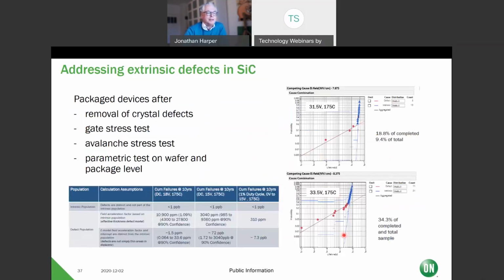So if you look at the classical papers on oxide integrity, you have the intrinsic oxide integrity, where you've got the oxide and you assume that it's perfect, right? What will happen over time? How will it break down? And you can run our devices at high gate voltages for short times. The long-term reliability would go down, but in principle, that's possible. So we have to do that for lifetime testing of that.